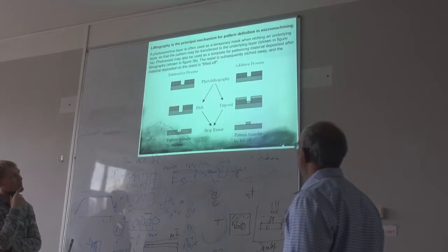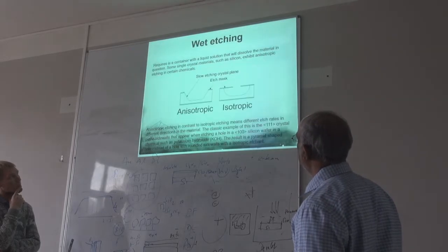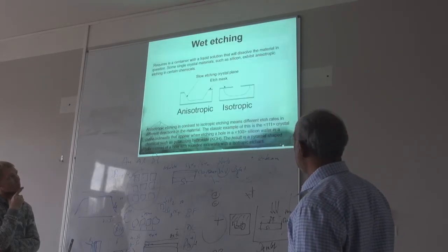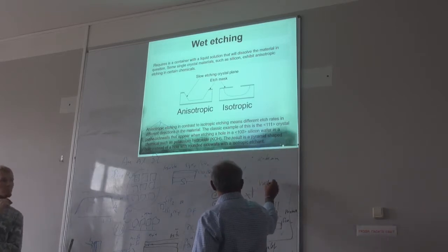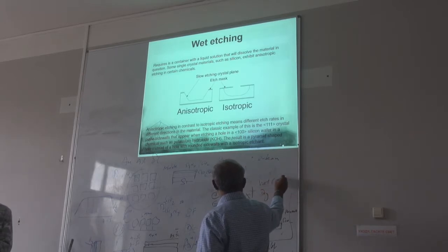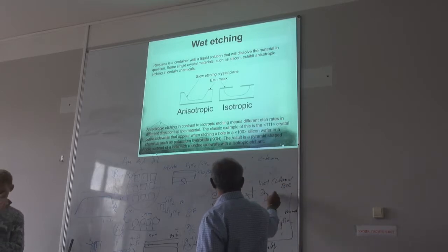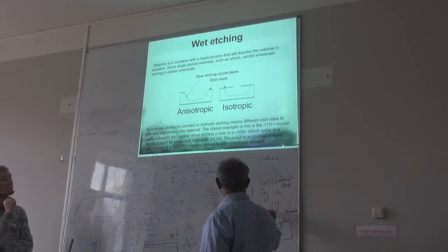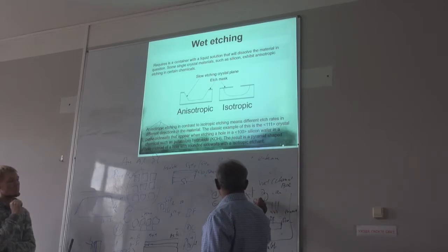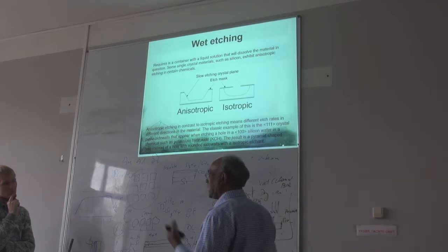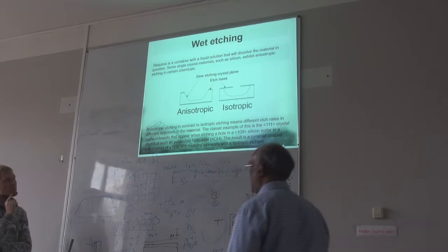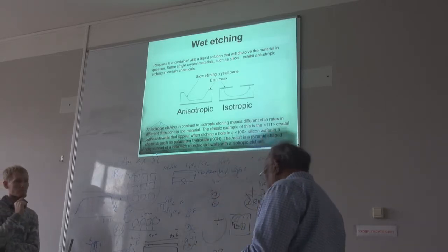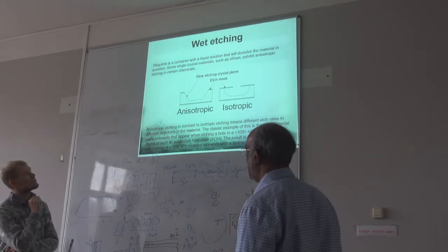Okay, so everything we talked about is this etching also. Like I said, there are two kinds of etching: one is wet etching, the other is dry etching. Wet etching is all chemicals, so we use the buffer oxide etchant. For dry etching, mostly we use what's called reactive ion etching, or we can use even a gas like xenon, and we can do deep reactive ion etching. If you want to etch deep into the substrate, then you have to use DRIE.